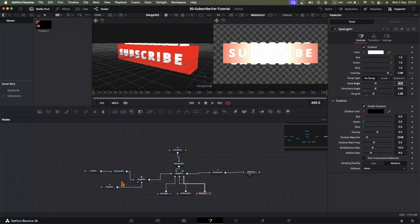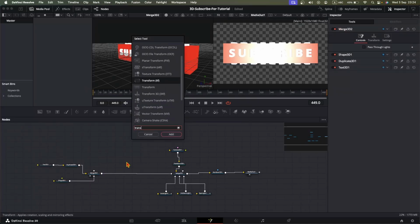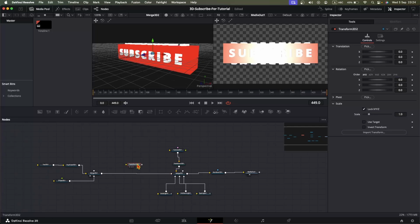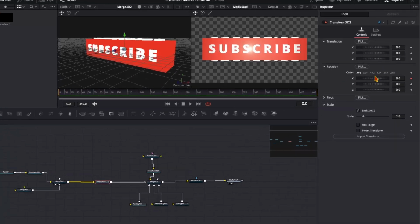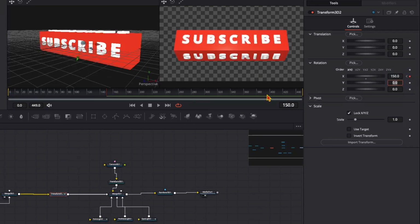The next transformation we need to do is after the merge 3D node of the text and the shape 3D, we will add the transform 3D node. Alt Shift, drag it and release it in between two merge 3D nodes. Now we need to animate the X rotation of this transform node. Go to frame 0, add the keyframe on the X rotation property, then go to frame 150. Change the value of the X rotation property to 150 and then go to the last frame of the animation and for the X rotation type minus 150.